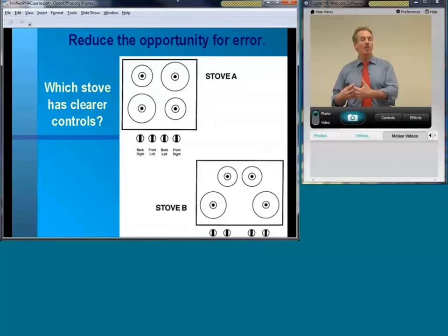But how much extra do 3 alarms, 4 alarms, 5 alarms help? One of the key things during a HAZOP study is you want to be careful when you're listing safeguards to only list those safeguards that are directly associated with the cause and are contributory towards improving the ability of the operator to respond.